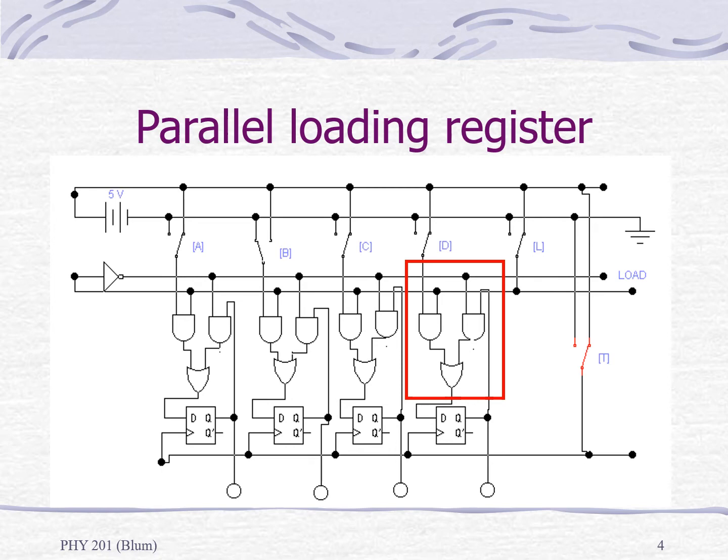The other part of this circuit is the T switch, which is connected to the clock input of the latch, and that has to go through an edge. We will write data to the latch when we go through a clock edge. L will determine whether we are getting that data from ourselves, almost a feedback hold, or from the switch. Then we're going to change the circuit to change this feedback hold into a shift. We'll think about that next.